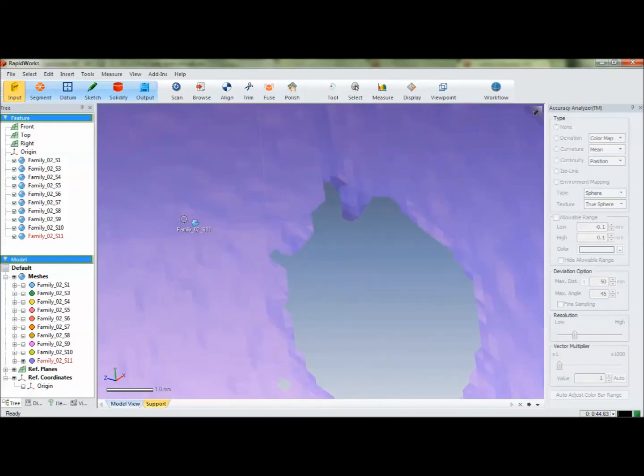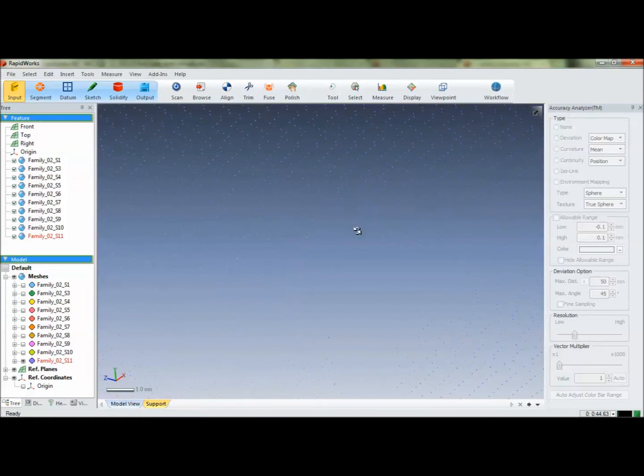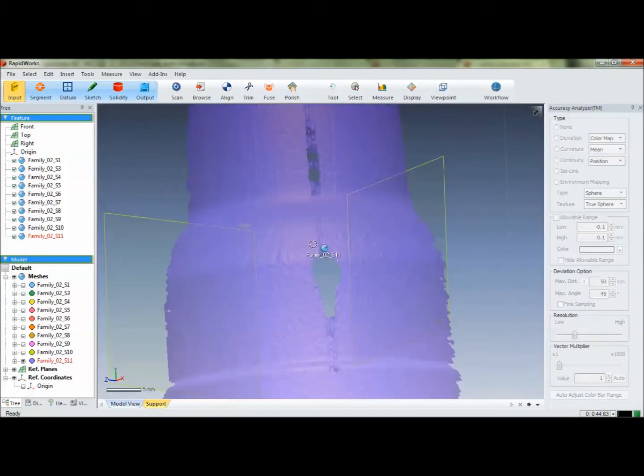That component will be smoothed in with these elements. So it's getting something that is a 1, 1, 1, 5, 1, 1, 1 numerically. So it's deviating all of this just to cater for that. So instead of doing that, I would rather just remove that complete component, get another scan from another angle that has this kind of surface, and lay that across that, and then merge the two together.